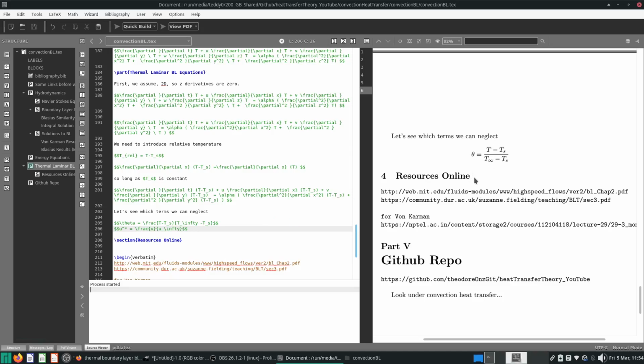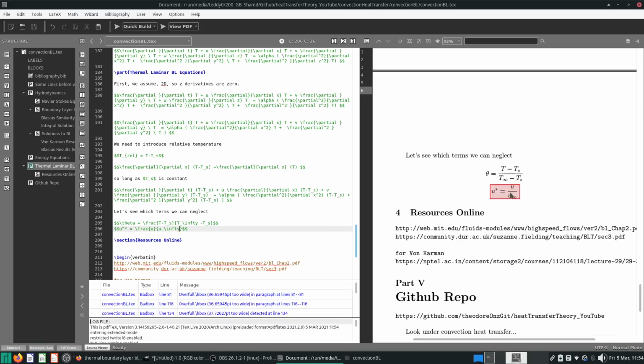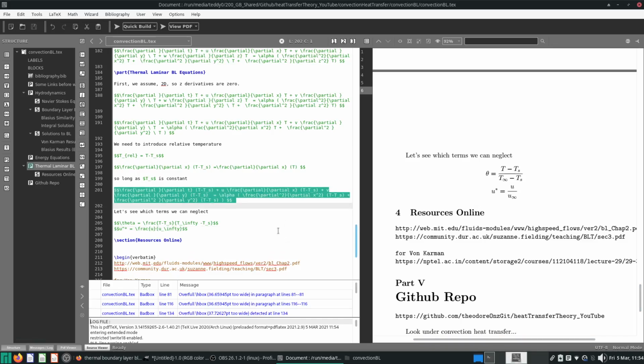For temperature, we like to use theta. This u is the relative velocity anywhere in your free stream; it's actually u minus 0. Then the free stream relative velocity is u infinity minus 0. They are both relative to the flat plate. So in case you're confused by the extra minus signs here, don't worry about it. They physically mean very similar things.